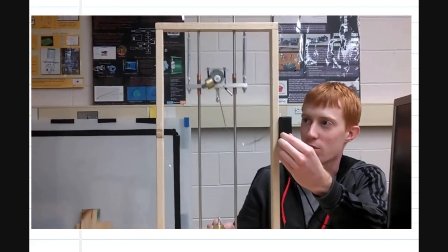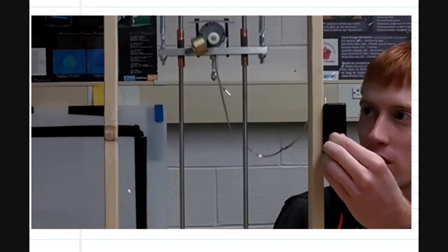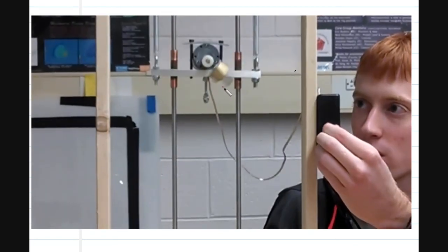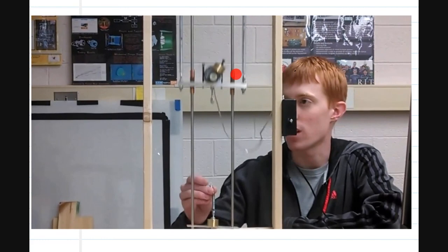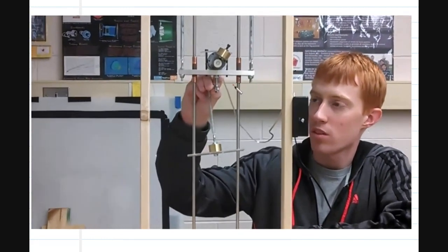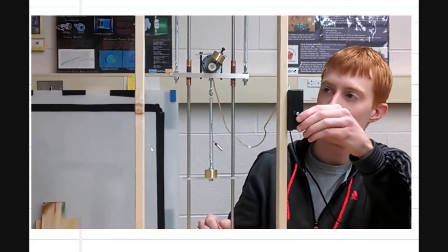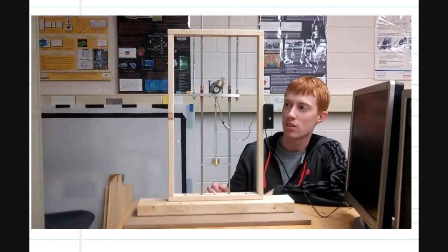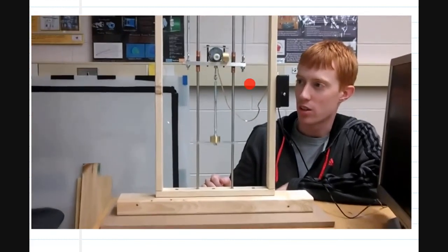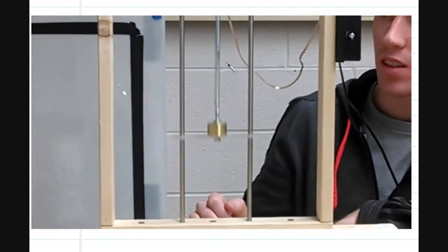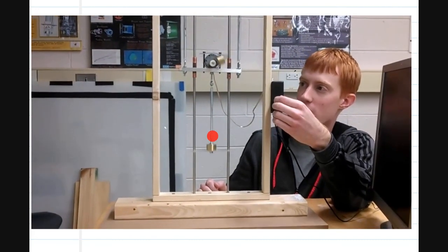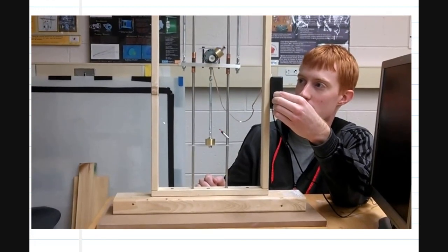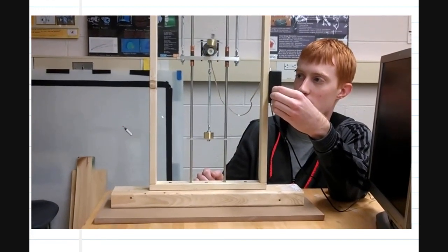Look at this, its very high amplitude gives you an idea that it is resonating. Clear? He is changing the frequency. This is a very high amplitude, so it's basically a resonance. Now at the same time, he attached a tuned mass designed using the previous equation, and look at this. At the same frequency at which the mass was vibrating before at a very high amplitude, it is reduced to almost 0. The frequency is the same, but now you can see your X2 starts to vibrate. That is an advantage of using a vibration absorber.